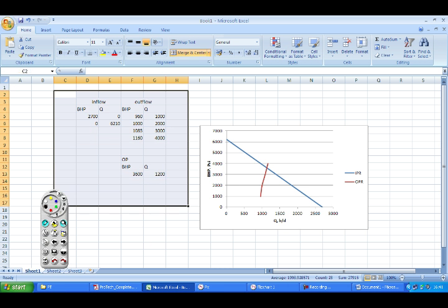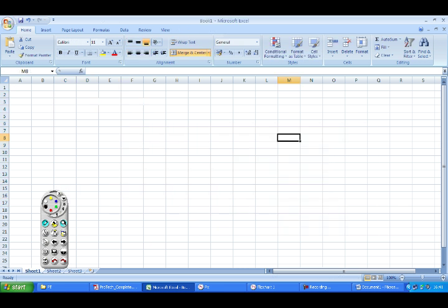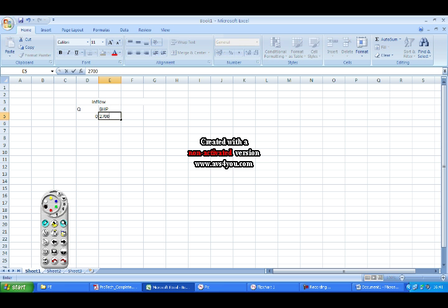Right, I'm about to find the curve for inflow performance relationship, and I will be plotting my rate on the horizontal axis versus my BHP on the vertical axis. If I'm not producing anything, my BHP, as I said, will be equal to my reservoir pressure, which is 2700 psi.